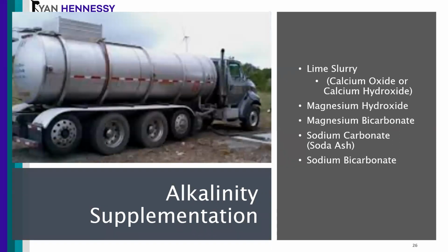So, for example, a lot of treatment plants that have very high BOD concentrations tend to have pH values in the effluent of closer to 8, because there's just more of those organic acids that are oxidized, creating that bicarbonate. So if there's not enough alkalinity present, as we mentioned, that's going to decrease the pH, and it's also going to eventually inhibit nitrification from happening.